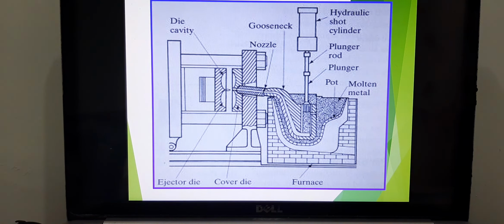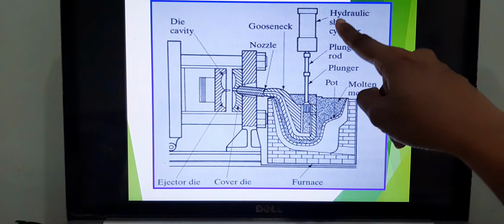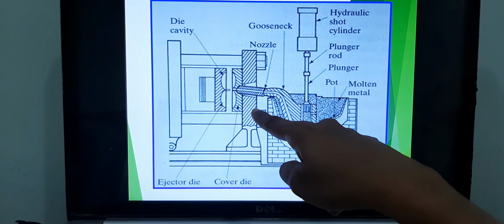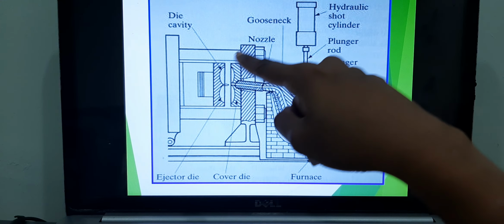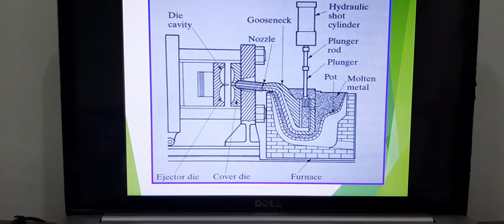If you look at it precisely, if it takes 25 minutes for solidification, the entire process itself may only cost you about 30 to 35 minutes from the time it started until the liquid metal flowed into the cavity, mold closed, apply pressure, allow solidification. Once solidified, release pressure, open up the mold, right? As compared to sand casting, where you need to construct the cope, construct the drag, test the sand, so many tedious processes, the same exact part that you produced in sand casting can be produced in die casting in a much shorter period of time.